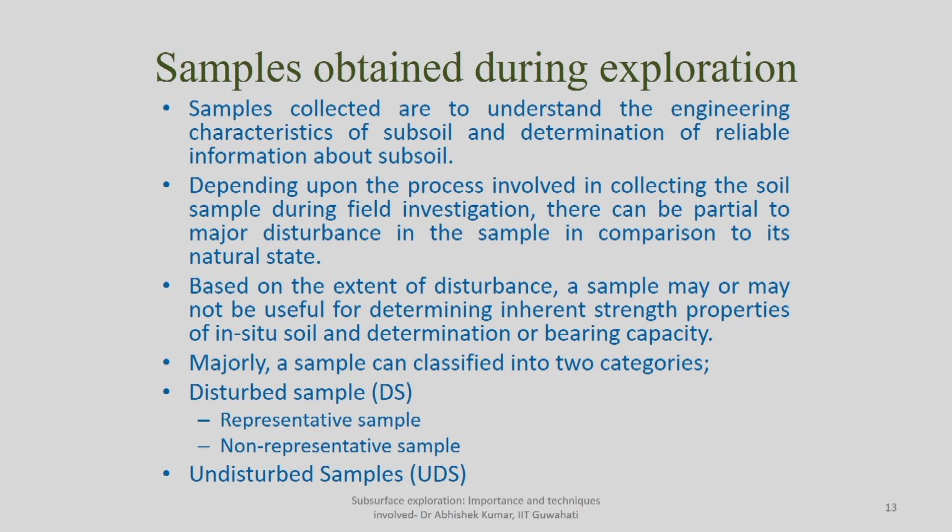It is like every 1.5 meter interval you collect a soil sample, whether the soil medium remains the same or changes. But in order to reach that 1.5 meter interval, you have to have some arrangement which can advance your borehole quickly. You can go there, collect the soil sample, then again do the boring exercise, same thing which I have been discussing earlier. So overall, whether you are going for auger boring, wash boring, percussion boring, or any kind of sampling, each time you are getting some kind of soil at the site.